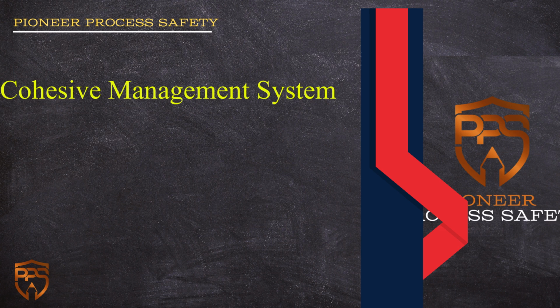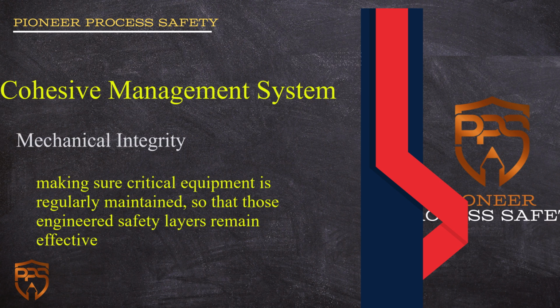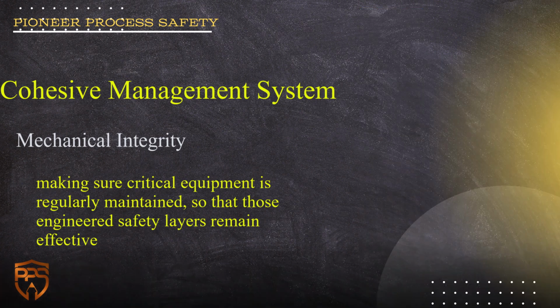Another element is mechanical integrity, making sure critical equipment like pressure vessels or relief valves is regularly maintained so that those engineered safety layers remain effective.